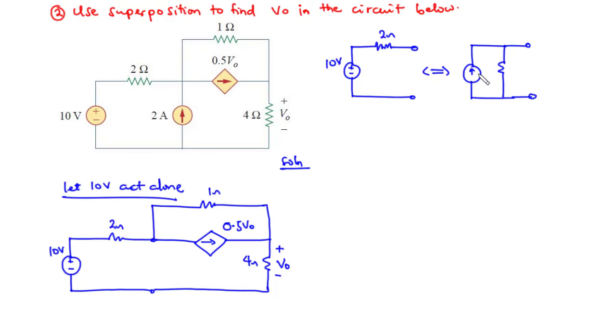So if you want to find the value of the current source, basically we are going to use Ohm's law. So from Ohm's law, we have V is equal to I times R. Now if you want to find the value of I, then it's nothing but V divided by R. You have V to be 10, you have R to be 2, so this is equal to 5 amperes. So you have this to be 5 amperes in parallel with 2 ohms. So this is how the principle of source transformation works. So we are going to deploy that here.